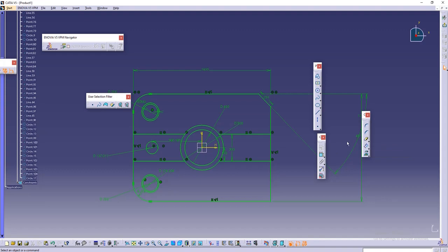This is another tool, the project 3D element. Right now we are just using 2D sketches, so there is no 3D element, right? This tool is used when you already have some 3D element in the background, and maybe there is a cylinder, and then inside you have to create some kind of sketch, and you need some reference from that cylinder. At that time you can use the project 3D element. It will detect, okay, the cylinder side line and the top line. It will identify and create a line, and then you can create the reference. We can explore it when we move to solid modeling, right?